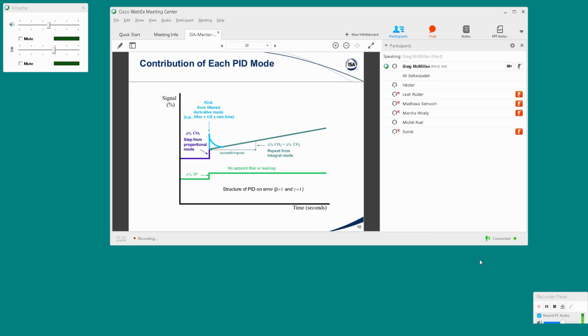Right. Yeah. And my familiarity with the relay oscillation method was that if you do it right, the oscillations across set point are very tiny. In fact, you have to make sure that if you want to see them, you zoom in on them to look at them. But yeah, I think in general the tools today allow you to do these tests in automatic, and I think the manual tests are mostly if you're trying to understand what's going on just manually. Okay. Yeah, good question.